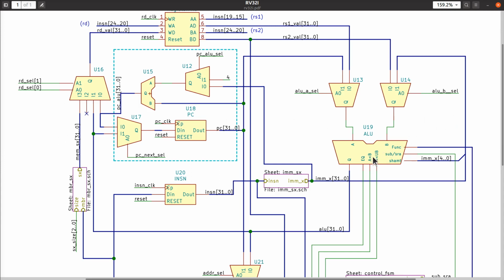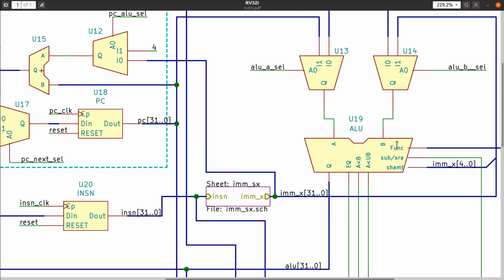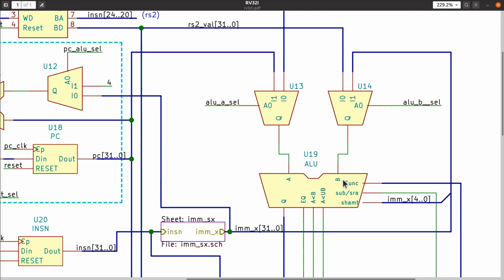Or we can take our ALU and create more functions, right? Now, there's really no reason we couldn't alter the multiplexer that we know is inside this ALU as part of its output stage and make more inputs. Let it do more functions. No big deal, right? One of those functions could simply be B.